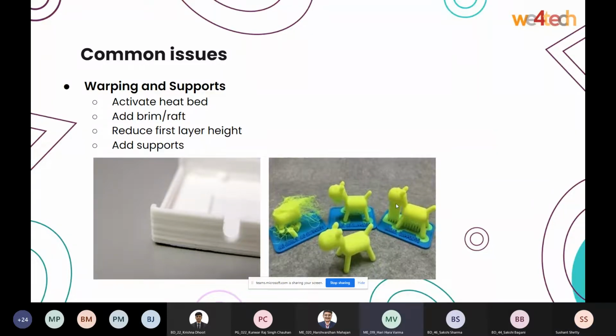All right. So make sure that whenever you're modeling and you're trying to print it on your printer, you can actually view your model in the software and see if your model requires supports. If not, then it's really good. As a precautionary measure, we always add these rafts to it, and in case you have something which is being printed in air, the supports then come to your rescue.